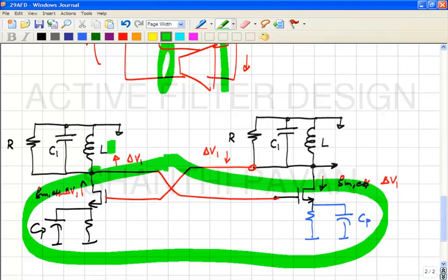And why did we connect the transconductors that way? Because we were interested in realizing a gyrator for differential signals, right? And each transconductor has got a common mode feedback loop stabilizing its output, but unfortunately when these two transconductors are put together, there is a positive feedback loop for common mode signals.